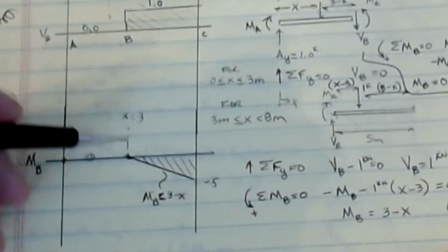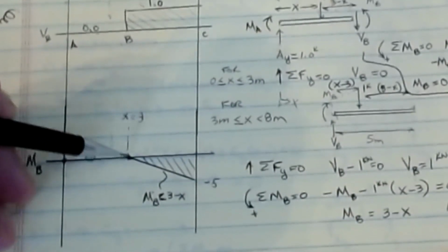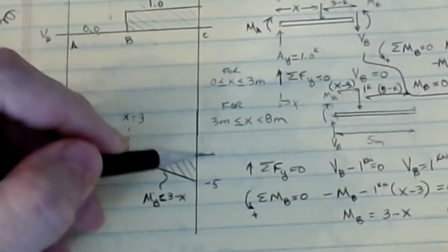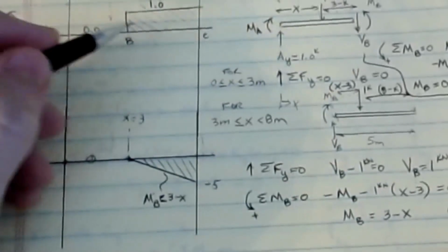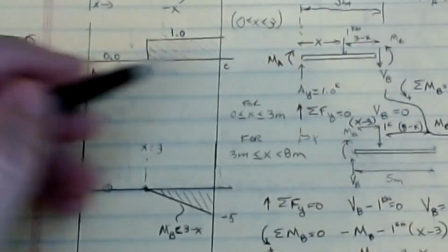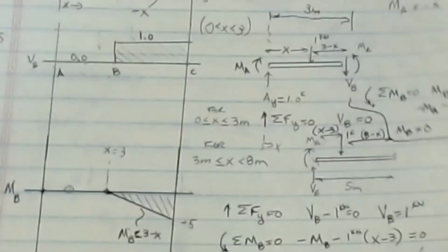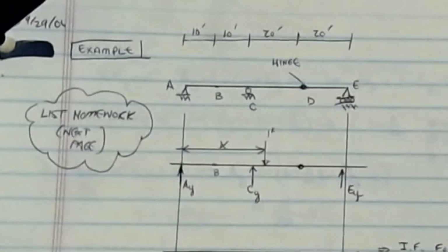So we know that to get the maximum moment or the maximum shear in this point on the beam, I would want to put the point load here to get the maximum moment, and I could put it anywhere to get the shear. Okay, that would get me the worst case because it's a constant shear on this cantilever. Okay, so I hope that made sense. Okay, all right, now let's go try one more. Okay, and this one, now we're getting into something that's a little bit more complex.